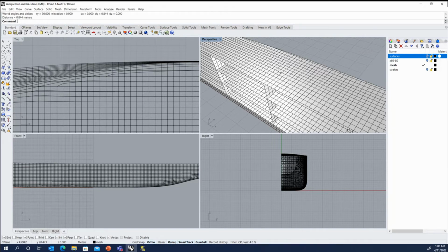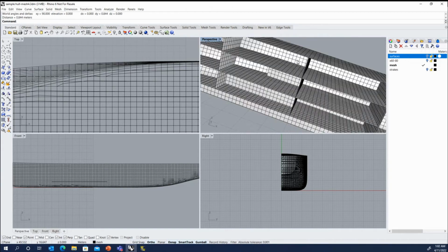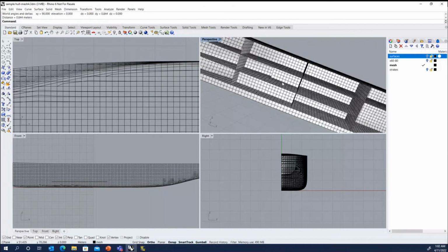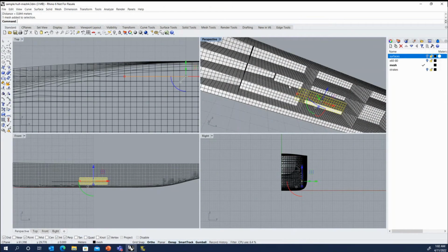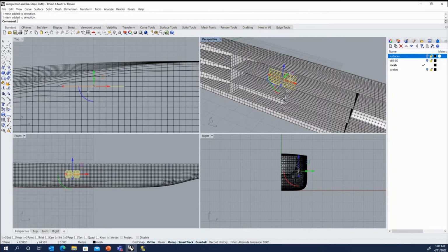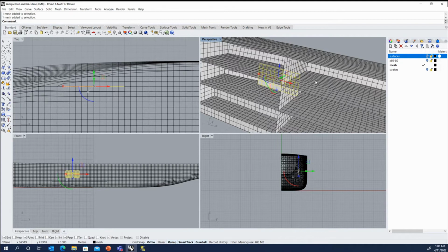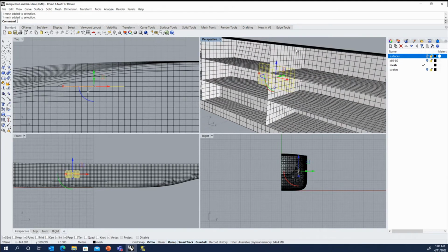So essentially, the next 5 meters, because we have a bulkhead at 10 in that area, that bulkhead is at 10 meters. This one is at 8.375. So the spacing that we selected, and we put this on every deck so that our transverse bulkheads would have vertical lines for our stiffeners on the transverse bulkhead.